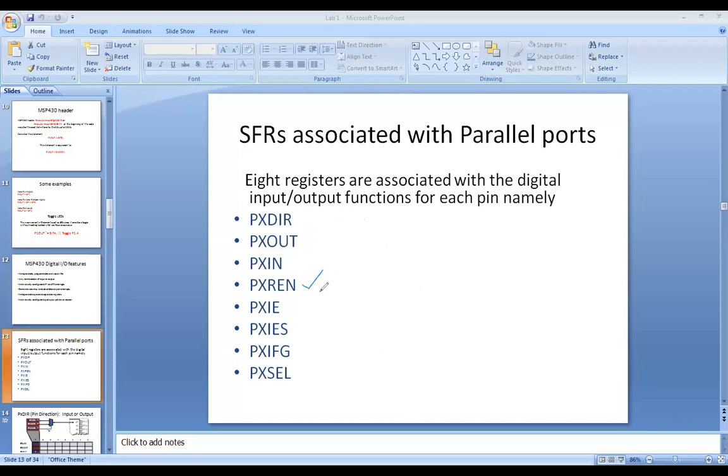Resistor is available here. So when we want to talk about a switch, a push button switch in this experiment, you have to read from the switch, am I right? So the MSP has to read from the switch. So this should be an input pin.